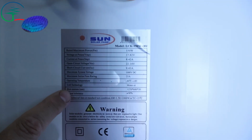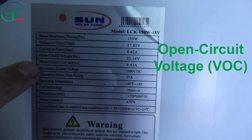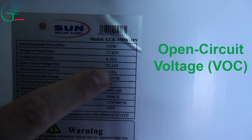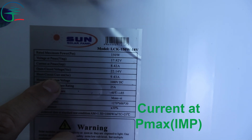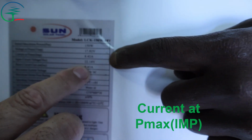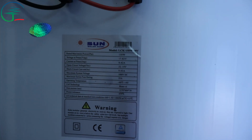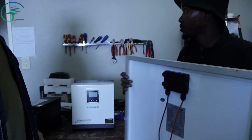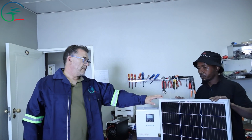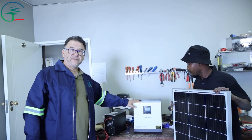You look at the VOC voltage, which gives a value of 22.14, and then the IMP current, which is 8.43. You look at those two values when you want to configure your solar panels with your inverter.